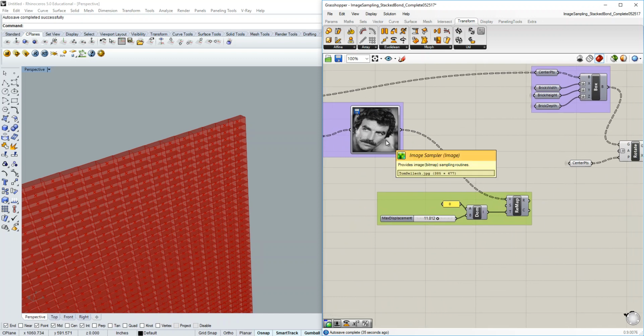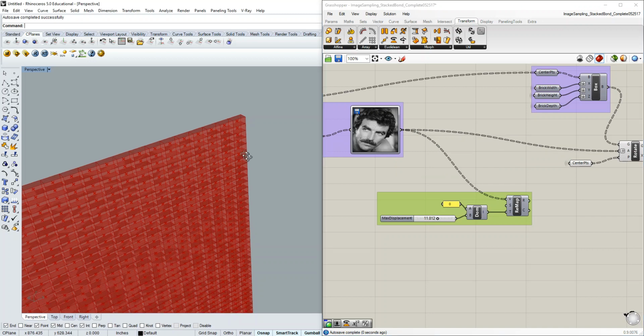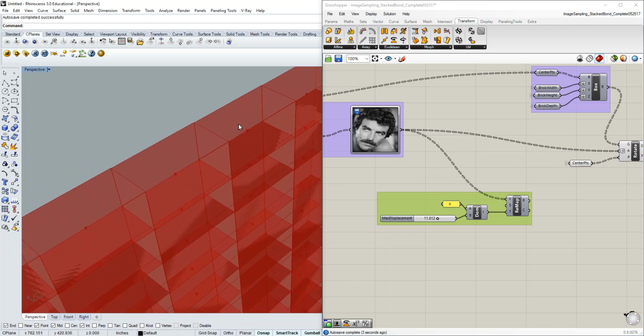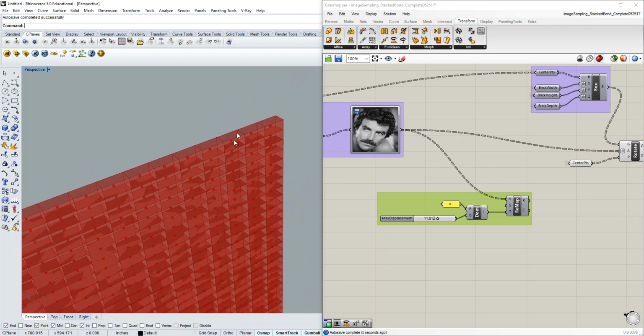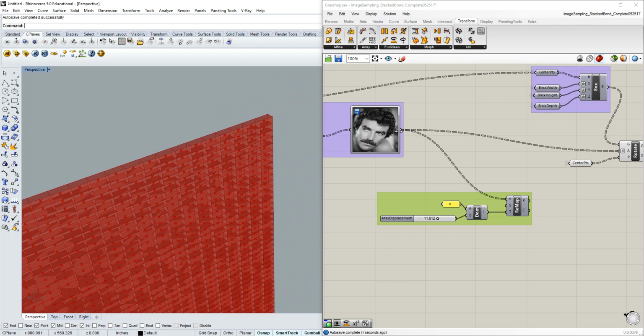By default, the image sampler is giving us a value between 0 and 1. However, if we simply use that 0 to 1, that's not going to have a whole lot of impact on the rotation angle. It's just not strong enough, it's not great enough, okay? So we can't really use that 0 to 1 value. We want to increase it, so that's where this remap is happening.